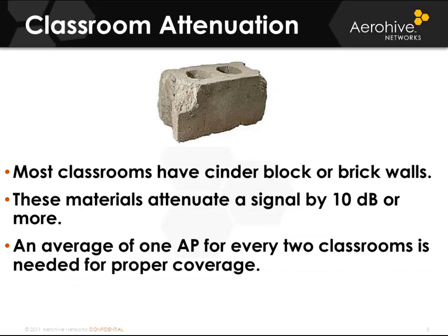A very challenging environment is a classroom environment. Deploying in the educational vertical can be quite difficult because often the classrooms are separated by large cinder block walls. These cinder block or brick walls often have additional materials inside the brick as sound baffling to keep the noise down between the classrooms.